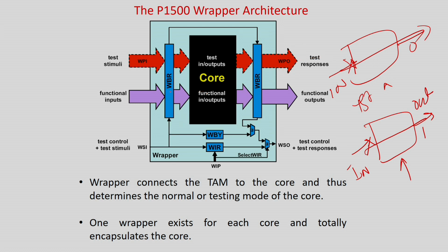So I either configure these registers to go in the functional mode, and in case of test mode, if it's a serial mode, the values will be traveling in this one, and maybe I require a 1 over here, 0 over here. So this serial I will be applying, and this functional input will be cut in this manner. And then the output will also be appearing in this functional output, and it will be scanned out. That is actually a serial way of doing it.